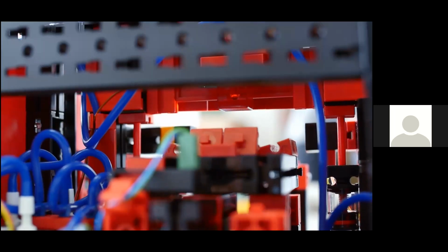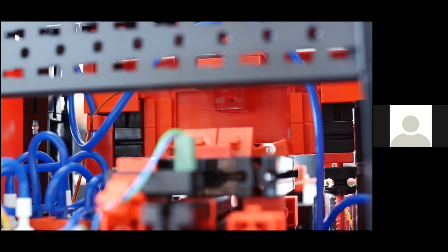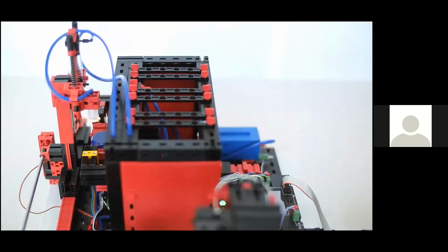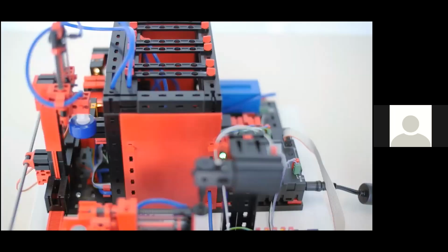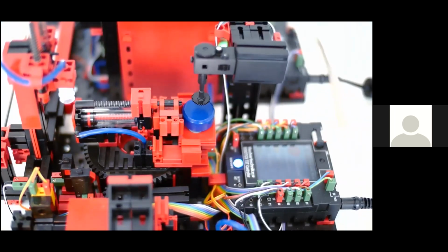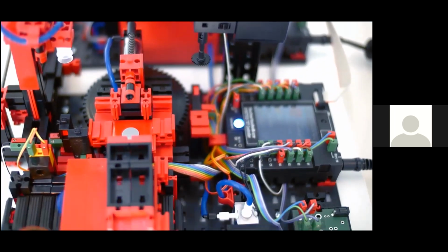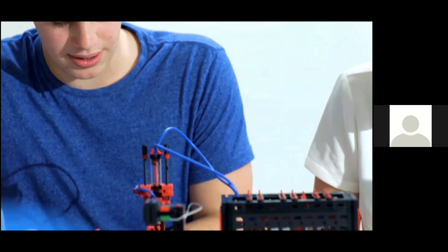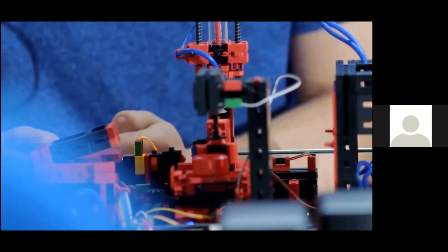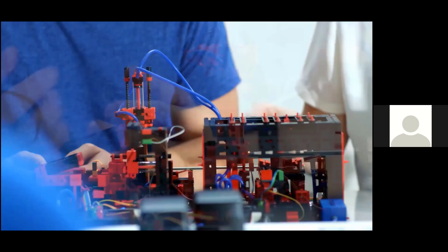The dimensions for the model are approximately 20 by 14 by 12 inches and it has a weight of about 11 pounds. Again, the standard version of this model is a 24-volt version for use with the PLC of your choice with, once again, a relay board for motor polarity reversal and both a multi-pin connector with 34 pins and a grid of 2.54 millimeters, as well as additional PCB terminals with pushing connections for all inputs and outputs. And again, the limited edition 9-volt version is available. In this case, it is connected to 2 robotics TXT controllers. And because of this, 2 120-volt power adapters will be required for all operations.